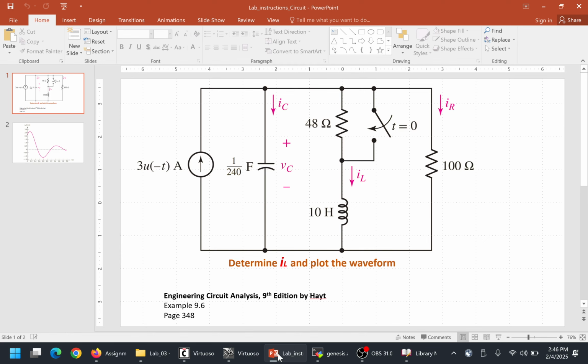So go ahead. Why did you choose 10 volts? Normally these kind of switches are activated at 5 volts. I just chose 10 volts because sometimes when you're solving a complex problem, if you have a 5 volt switch somewhere, the matrix gets 0, somewhere the determinant becomes 0 and the solution becomes unstable. So this doesn't matter. It can have 5 volts, 7 volts, 10 volts, it's just a number. Yeah, but more than 4.